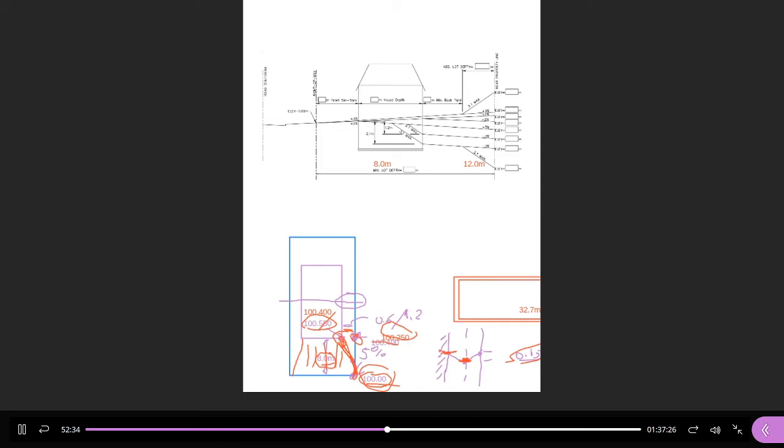So when we go back to my sketch, you'll see 2 minimum, 3 maximum. And the reason I'm using 3 and not 5 is because I'm worried about what's going to happen inside the lot when the architect designs the actual space of the lot, not the sides, which is all I'm responsible for as the civil designer. Any questions about that? Does anybody not understand that exercise?